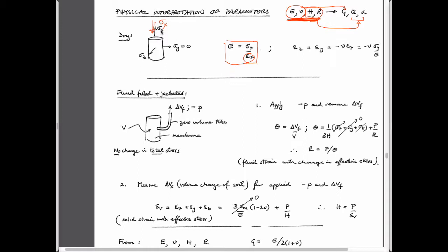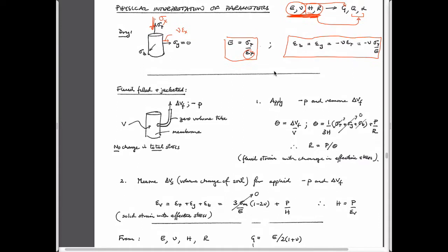And as we apply this, the strain in the horizontal direction will be equal to Poisson's ratio multiplied by the strain in the x direction. These are just the straightforward, simple manifestation of Hooke's law where there are no fluid pressure changes present to mess things up. So that's the simplest way that we can look at it, and that's one thing that we can solve for.